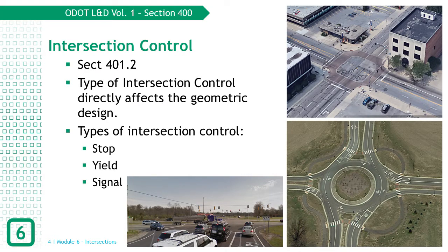Stop signs require everyone to come to a stop, so less stringent design standards can be used as lower approach and departure speeds should be seen. Signalized intersections offer the opportunity for a green light, which means vehicles could very likely negotiate the intersection area at the mainline speed, creating higher approach and departure speeds. Roundabouts offer geometric criteria that force lower approach speeds.